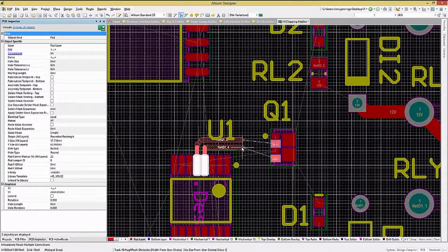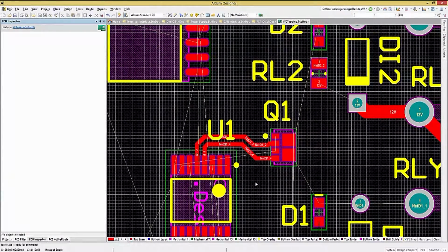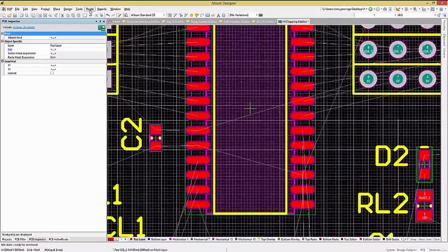Adding segment endpoints along the way by left mouse clicking can guide the placement of the group until the termination point is reached. Or when you get near the termination point, hold the Ctrl key down and then left click, and the tool will auto-complete the routing if possible. If you need to at that point, I would use the ESP shortcut again to select those nets and run the gloss to clean them up.